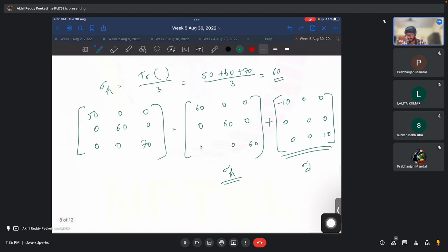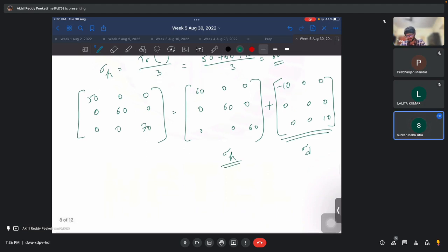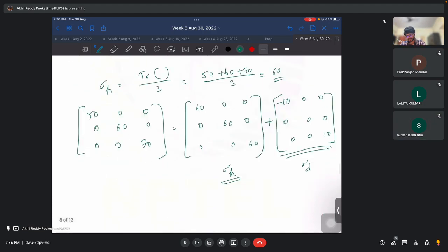So whenever any normal stress system is there, the hydrostatic component will be the case where all the stresses are equal and there is no shape change in the system. And then deviatoric would be the shape change, distortion component of the stress. So in distortion energy theory, we'll actually look only at the energy due to this distortion energy, and that is why you get that final equation.